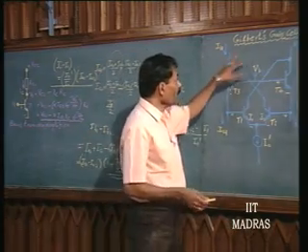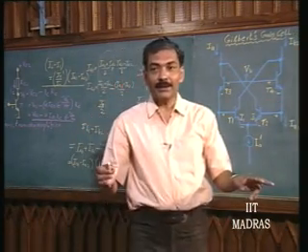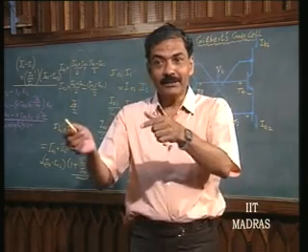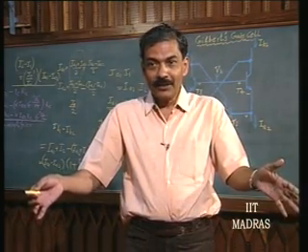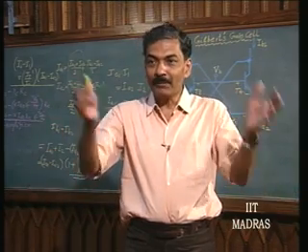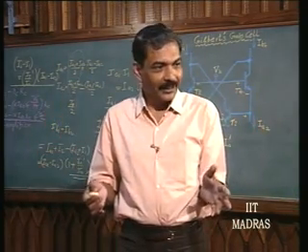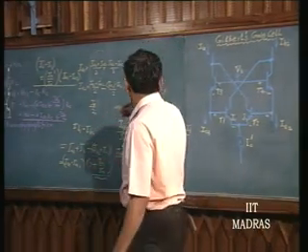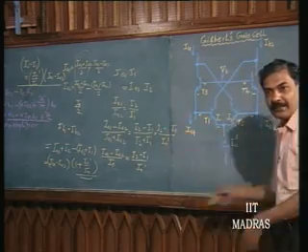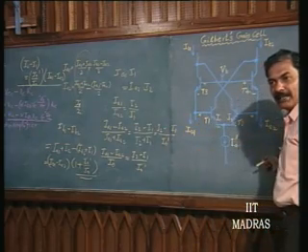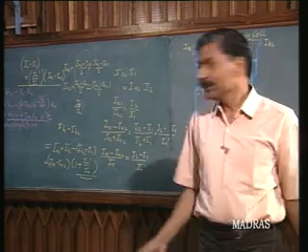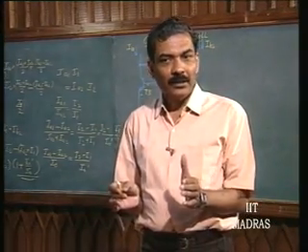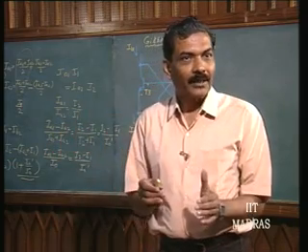and this can now become what? Please complete this. This can now become IA1 and IA2 for the next stage, which is exactly identical to this, only that it should be operating at I0 double prime, which is higher than I0 prime, in order to get a gain factor. So, this can become now the input current to another identical stage, and the output of that will be what? Again this as the input current into 1 plus, let us say, I0 double prime by I0 prime.